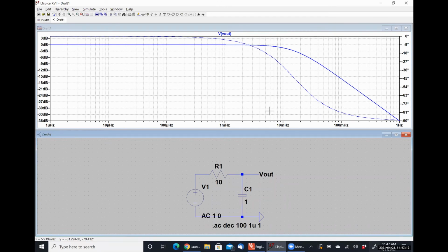So with 3 decibel tick marks, this is my 3 decibel cutoff frequency. Right here where my finger is, this is a logarithmic graph. So if this is 10 millihertz and this is 20 millihertz, this seems like a pretty good place for 16 millihertz to be, right? So we're getting exactly what we should expect.